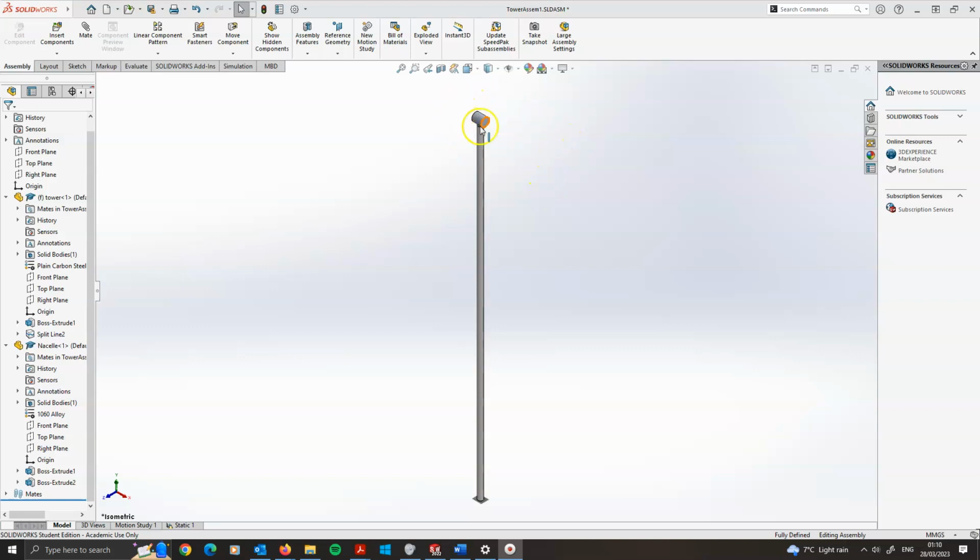So what we'll do is we'll measure maybe the displacement of the top of the tower at a range of different frequencies and measure the stress at the bottom of the tower and plot out graphs of the response of the system. Now we could just use some of the simulation nodes to track that movement, for example. I'm going to show you another way of doing that. We could apply what's called a sensor to the model.